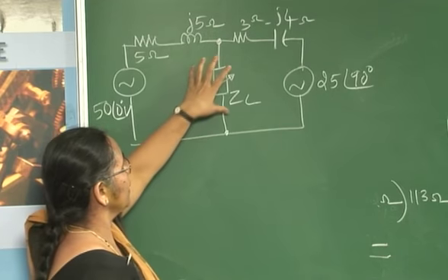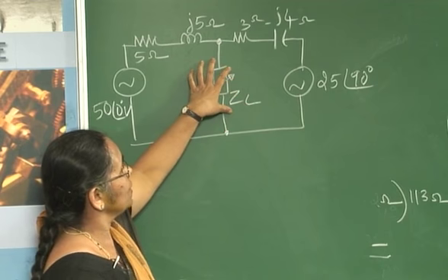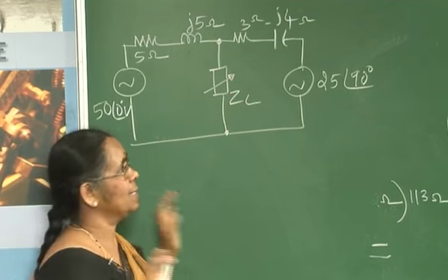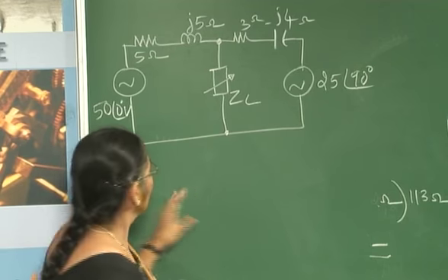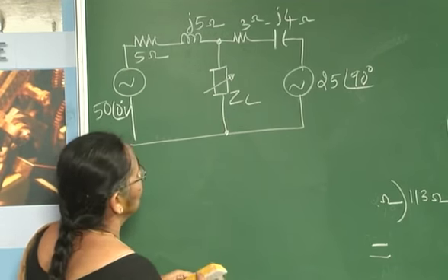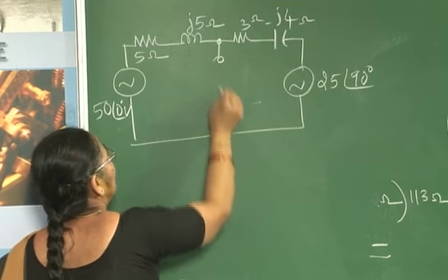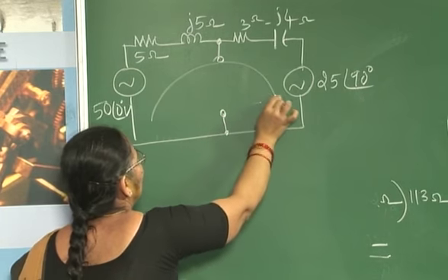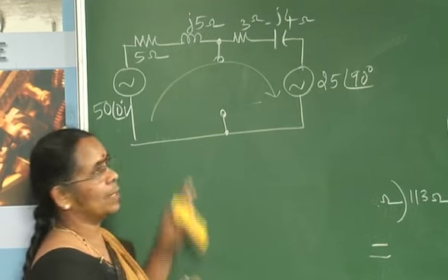So now the first step is to get Thevenin's equivalent circuit. After finding Thevenin's equivalent circuit, the next step is to find the Thevenin's equivalent impedance, and after that find the total power which is being transferred. So for that, first you have to find the Thevenin's equivalent voltage. So remove ZL from the circuit, creating an open circuit. So in that case, you are going to find a single series circuit. Only one loop exists there, only single voltage.